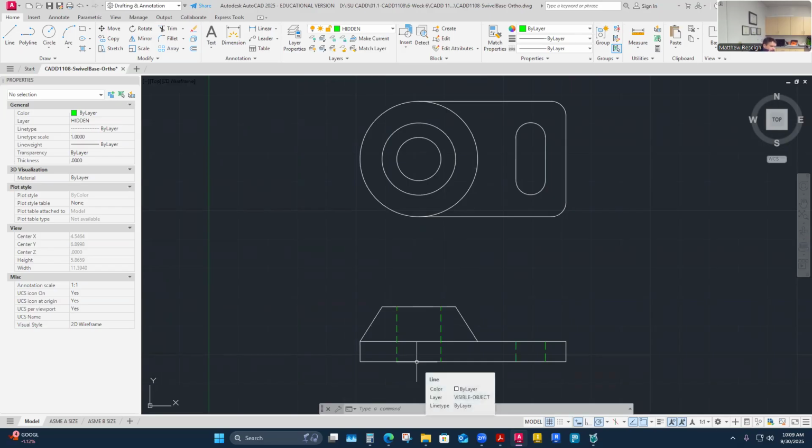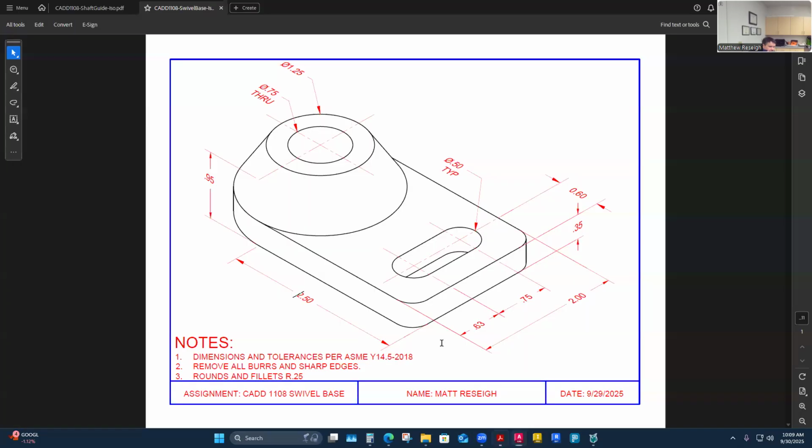I'm going to keep a line to delineate between the cone section and the bottom plate instead of cutting that out as smooth. It's really because I'm driven by what it looks like here. I would always have this line in the front view, that would appear as this curved line, and in the front view it's just going to look like a line. Then it would come across to this point, and where they've carried their solid line through, I'm carrying mine. So it's almost like they're delineating between these two. Otherwise, they would have trimmed out maybe this to make it look like there's a surface blend going on here.